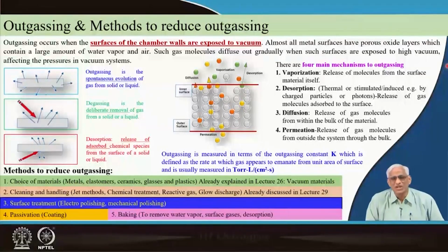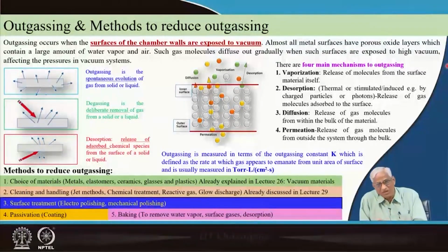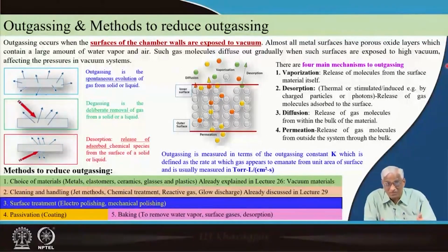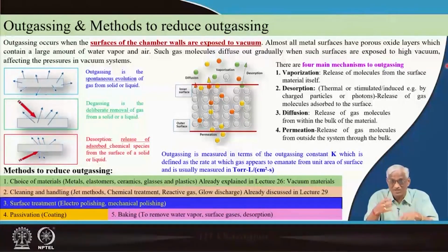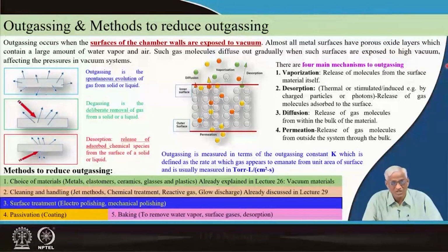Normally people do not care about this at 10^-3 torr, 10^-2 torr systems, because outgassing is not that big. Even in chemical and pharmaceutical applications, they call it air leakage. Leaks are more important, because they will interfere with your process gases. Chemical and pharmaceutical processes themselves have a lot of vapors, which are used for distillation or drying operations, etc. So, small outgassing or anything at the micro level from other things should not matter. Well, of course, if they are poisonous things, it matters, and you have to be careful.